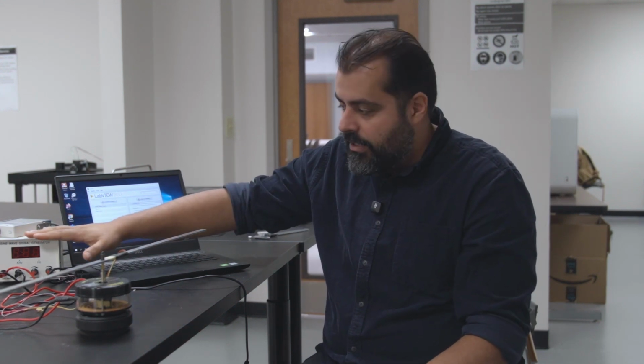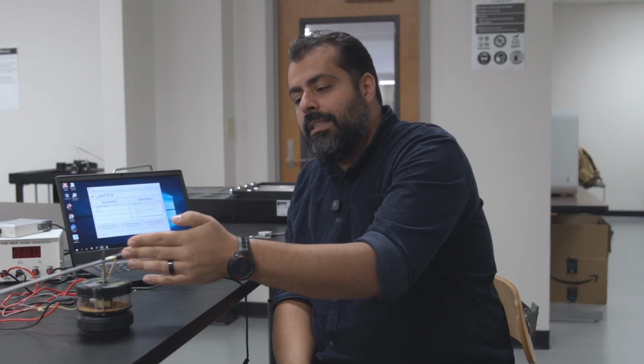So the first step would be to provide the frequency to the beam and set up the LabVIEW program to read the strain. At the end, when everything is ready to go, we are going to stop the frequency from here, and record how long it takes for the strain to go from a value to 0. We expect to see a dying sine wave.